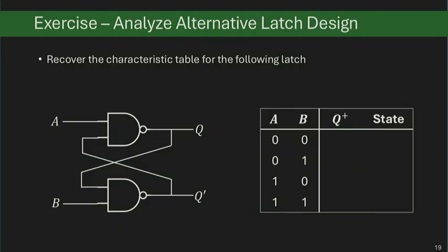And then I like to start with some situations where the input value directly determines the output of the gate. So for example, for a NAND gate, 0 is the dominating input. It essentially overrides the other inputs. Once you have a 0 at the input, the output will be a 1, regardless of what happened on the other side, essentially regardless of the previous Q and Q prime. And with 0, 0, I have both Q and Q prime being 1, so that is an invalid case.